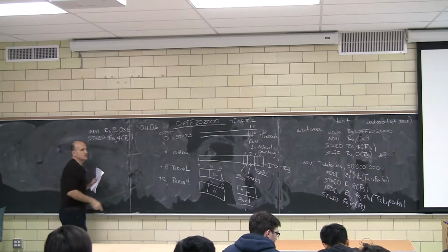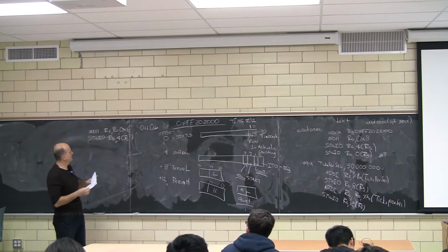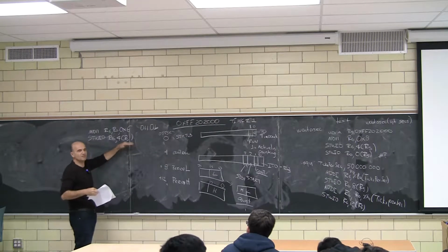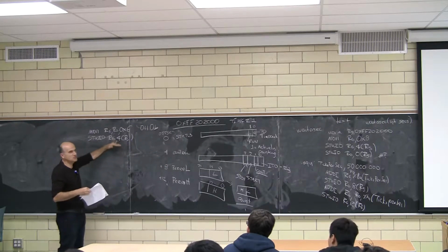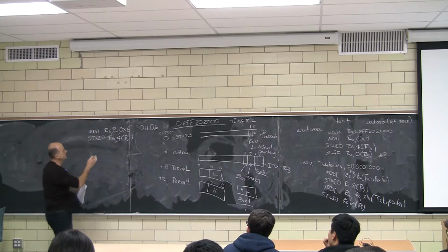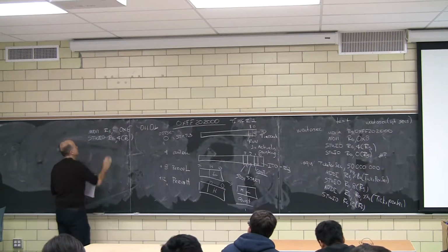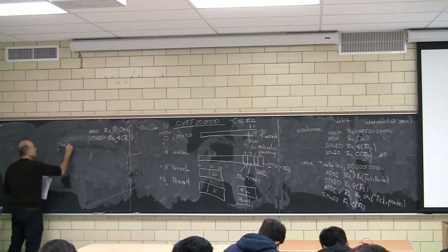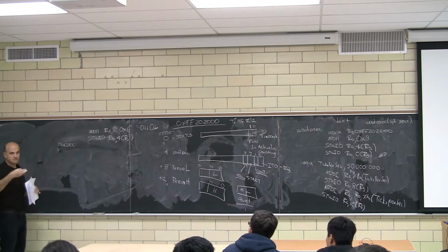So now the counter starts. Sorry, I forgot to say that. I created the constant, but I forgot to write it to the control register. Okay. So now the counter actually starts counting after this instruction. Does the move only take one argument besides R6? Yes. Absolutely. And now we go and we wait for 1 second. We're going to use polling here.